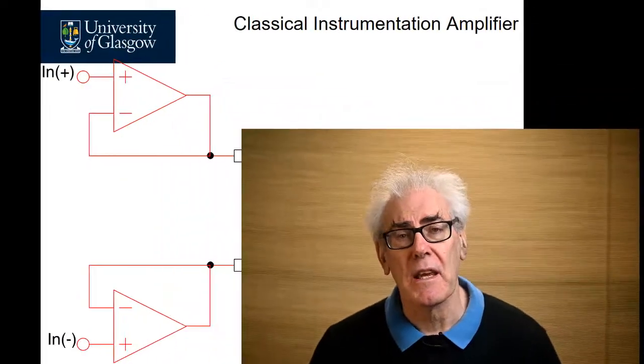In the first lecture on the instrumentation amplifiers, we looked at how you analyze them and the improvements in them. In the last lecture, we looked at how you can improve common mode rejection ratio and how to analyze common mode rejection ratio by improving the matching resistors. We also looked at how you can actually separate any errors from the sensor by buffering it via two buffer amplifiers connected to a classical differential amplifier. In this lecture, we're going to look at how we can improve the performance of an instrumentation